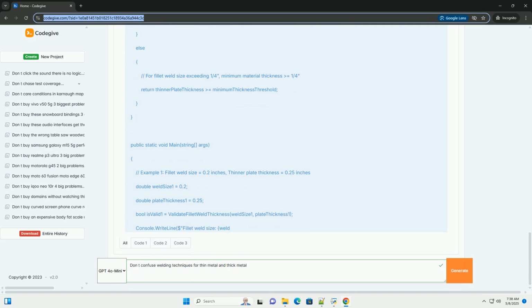ASME, American Society of Mechanical Engineers, primarily focuses on pressure vessels, boilers, and piping. ASME codes are very strict and require rigorous testing and documentation. API, American Petroleum Institute, covers welding in the petroleum industry, including pipelines and storage tanks. General code implications based on metal thickness: